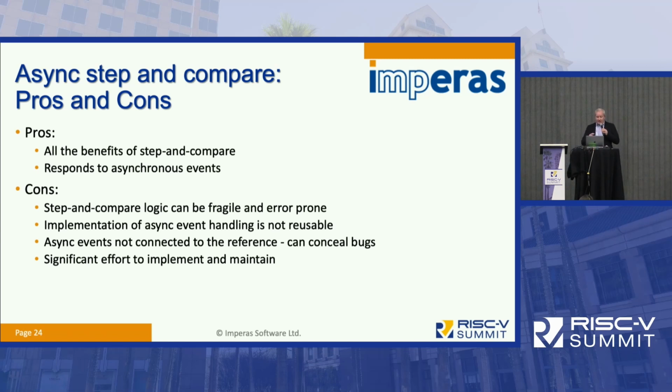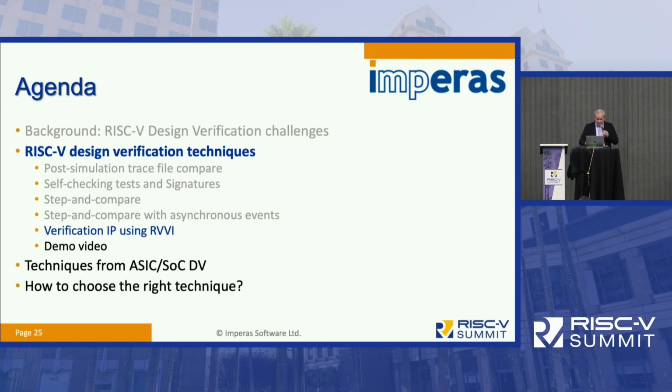The downside is this tends to be quite fragile because these are bespoke solutions to be able to pass this information. What they also tend to do is ignore a lot of the logic that is defined from the boundary of the device up to the introduction of those values into the instruction pipeline, and all of the logic that resolves the introduction of the asynchronous event.